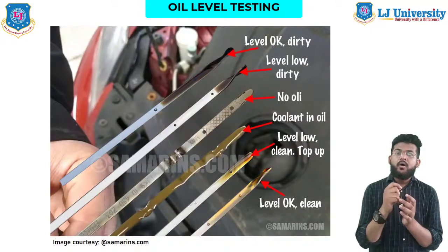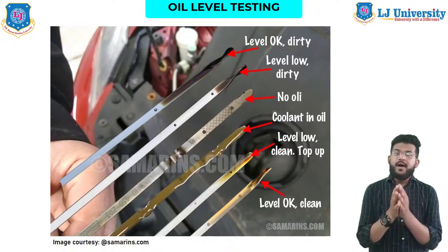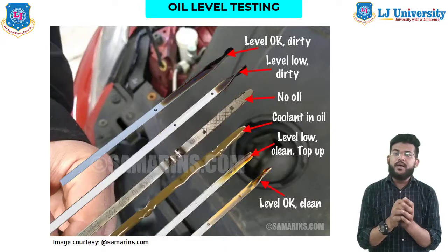If your oil is clean but only reaches the add part of your dipstick, you will need to add more oil. Now the process for how to check your oil is very simple and it involves using the dipstick to see the levels and the quality. So to find out whether your vehicle needs oil, just follow these steps.